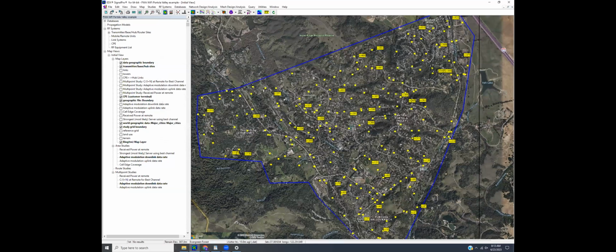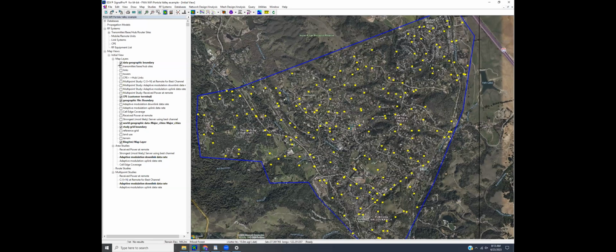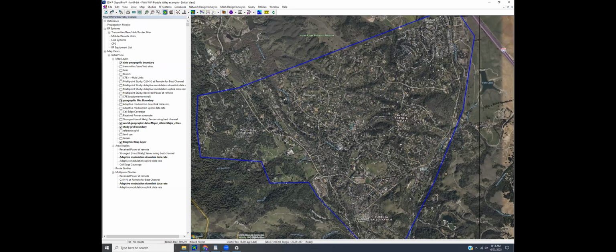And now in this example that I'm showing here, I've already got some access points loaded into my project. But one of the really key features that you get, especially if you have a large scale design that you need to do in Wi-Fi, one of the really great features that we get either for area wide or fixed point to multi-point cases are the automatic site placement tools. And if you have the Wi-Fi module, then you get those automatic site placement tools both for area wide. So in other words, I can define the template for what my access point looks like, and then go to databases, towers, and poles, and specify a list of basically all of my candidate tower sites.